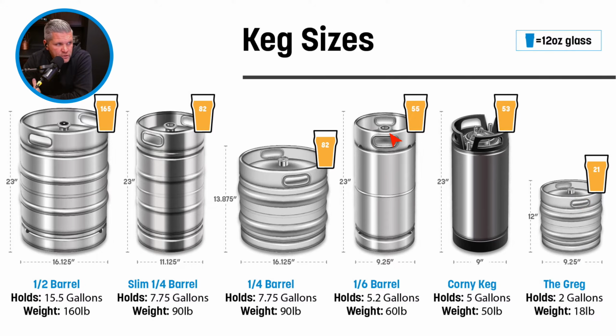Most of these that you get commercially, they have a locking ring on the inside of it, and the spear is not meant to be removed at all by anybody in the field ever. So these can be really dangerous. If you start pulling on those pins inside of here, like that keg, I've seen, we were at, I think, GABF one year, and we saw one of the spears leave one of the kegs, and it shot beer up to the ceiling in one of the convention centers. So they can be quite deadly. These are meant to be cleaned by caustic, by machines, so they're not meant to be opened by people unless you've got a threaded removable spear. So just a word of caution there.